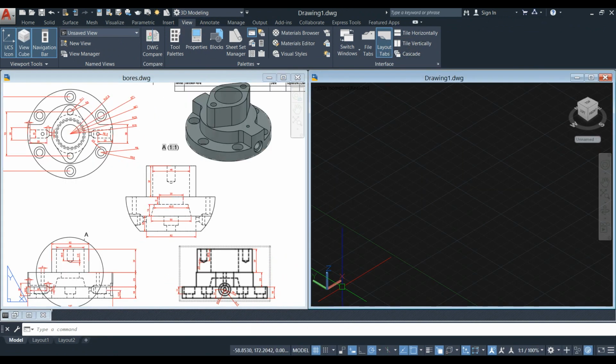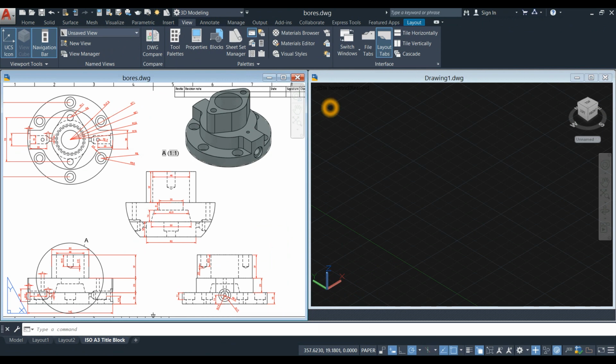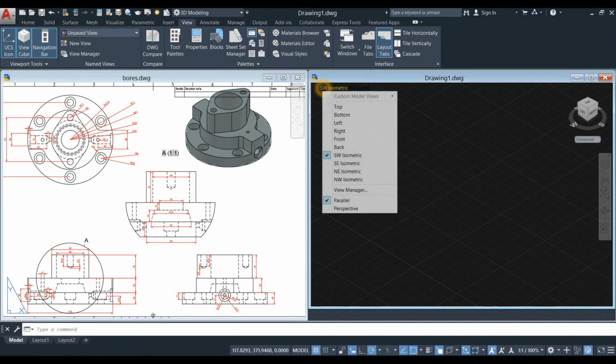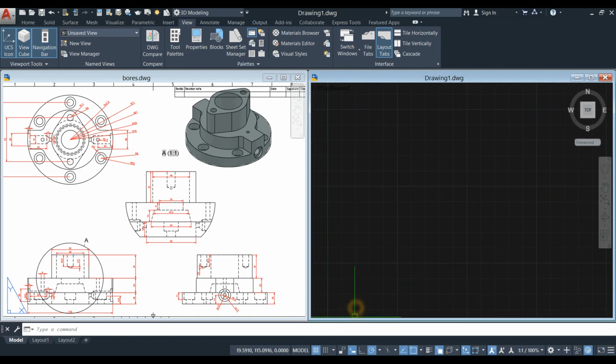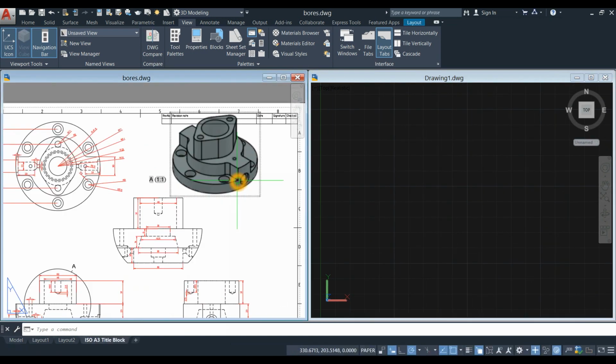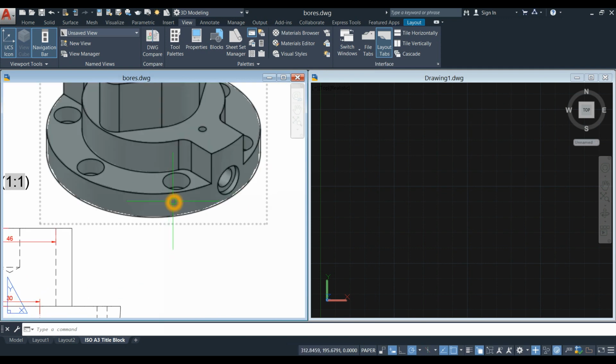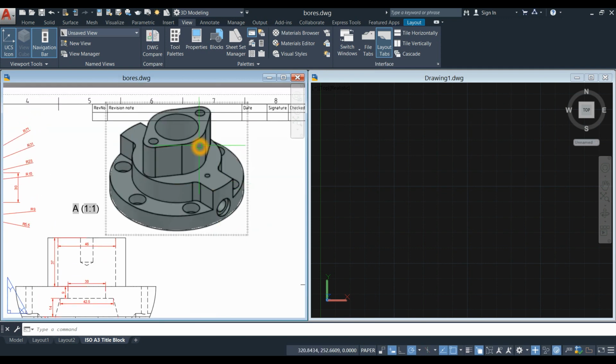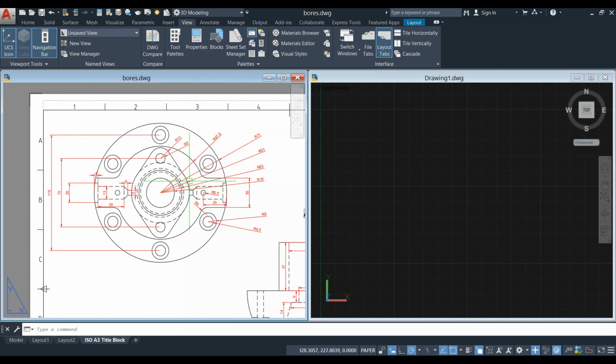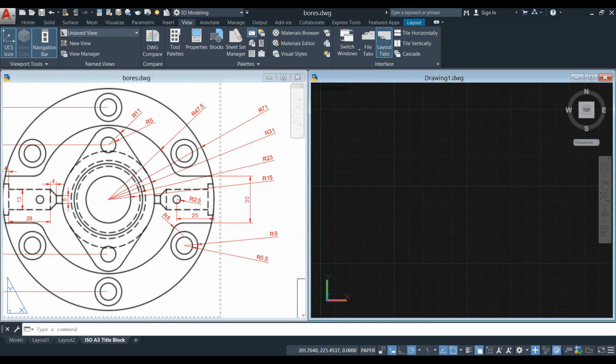I'm gonna start working from top view. So click the view controls and select top. I'm gonna split this object into 3 parts. So this one here and the middle part and this top one. So I'm gonna start with circle.